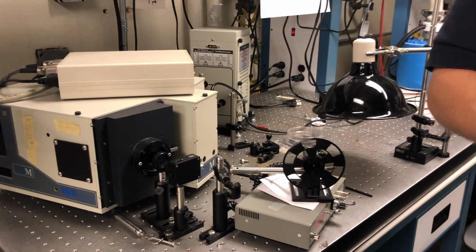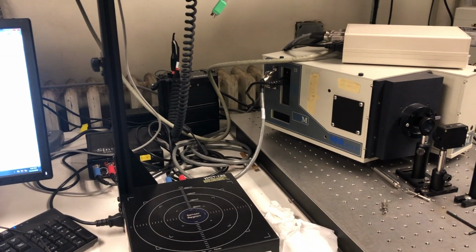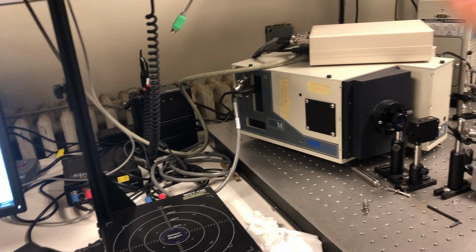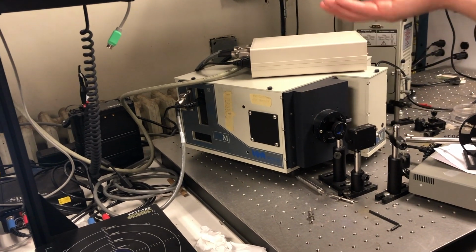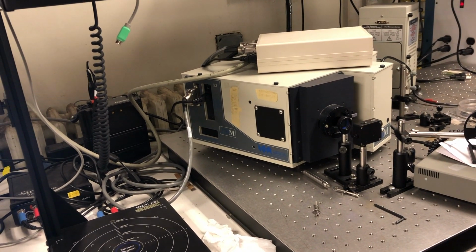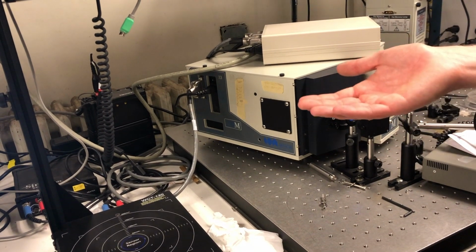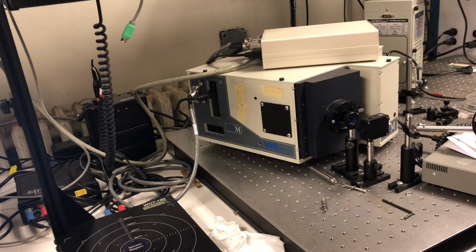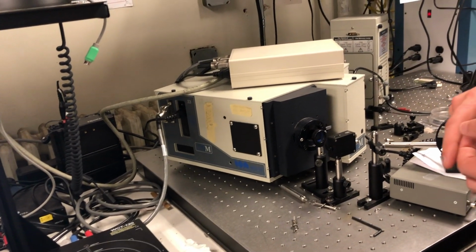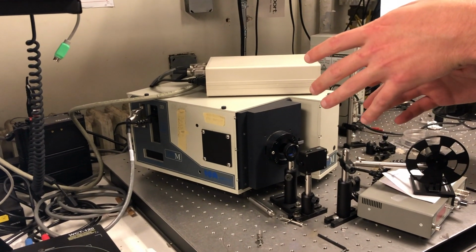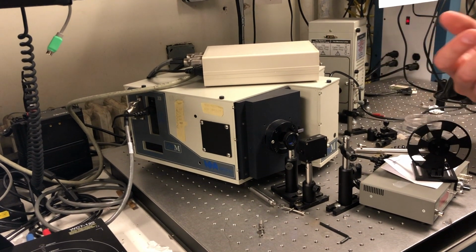Any questions? So what conclusion can you make if it doesn't perform well in a certain wavelength? Well, let's say your surface texture isn't helping, or maybe you've got some sort of layer on the front that you've deposited that gave you better electrical performance, but it's eating away at your current. You can determine things like that. Again, if the back of the cell is bad, it's usually the red which will be affected, because red will penetrate further in the device, and the blues will be more absorbed in the surface. So depending on if you see a spectral loss in efficiency at either of those, you can assess which layer is being affected. It's not perfect, but it's one way of doing it.